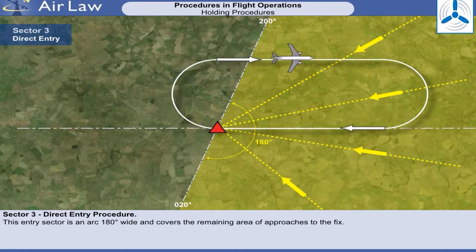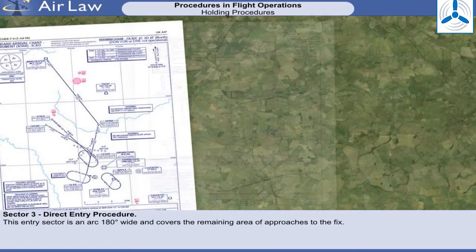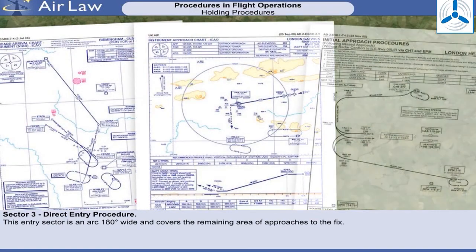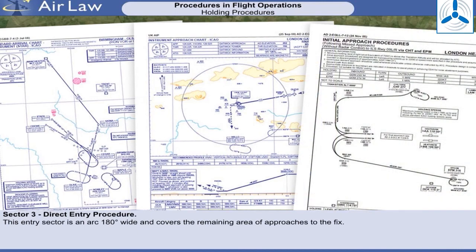Again, and this is the most likely scenario, especially for student pilots, the Sector 3 direct join is permissible for magnetic headings of 195 clockwise through 025. This completes the 3 entry procedures to a hold. Holds do vary in their orientation, segment length, speed and direction, so be familiar with the holds at the arrivals area of your planned and alternate destinations.